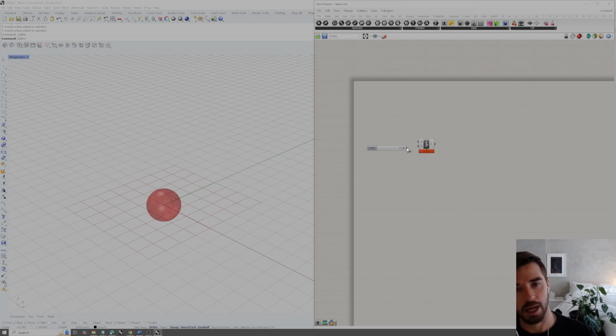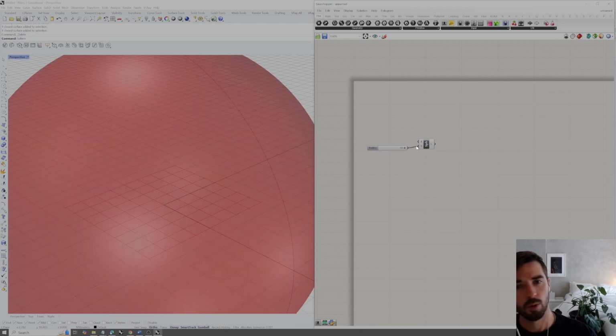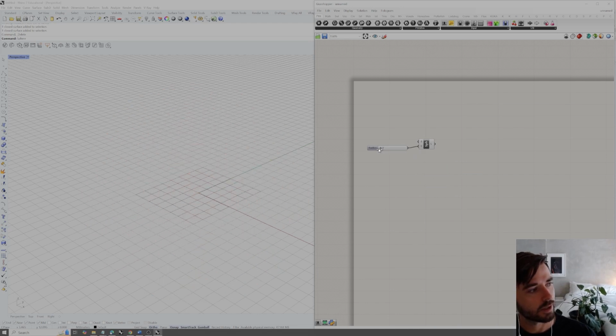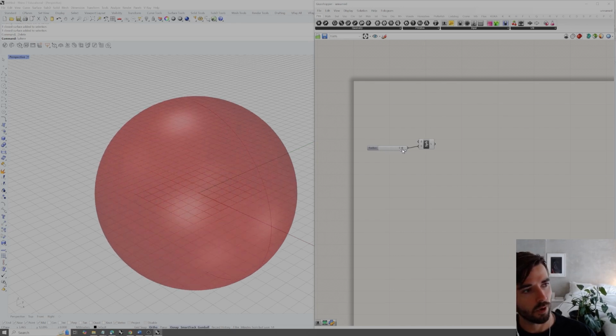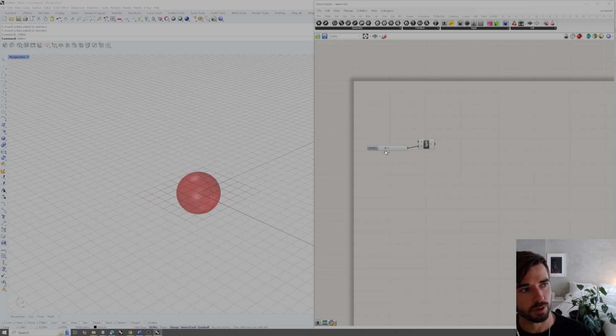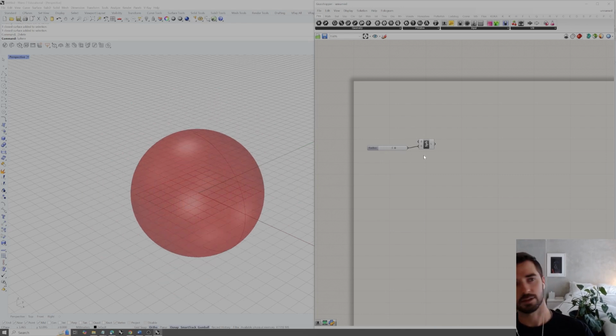If I plug this output node, so this kind of end node on this component, into the node for our input radius to the sphere, we'll see that sphere automatically update. And if we hover over the radius, we now see that that value has changed to 10. As I slide the slider, it dynamically adjusts from 0, which means non-existent sphere, to 1 to 2, all the way to 10. So this is going to give us that parametric variable control inside of Grasshopper.